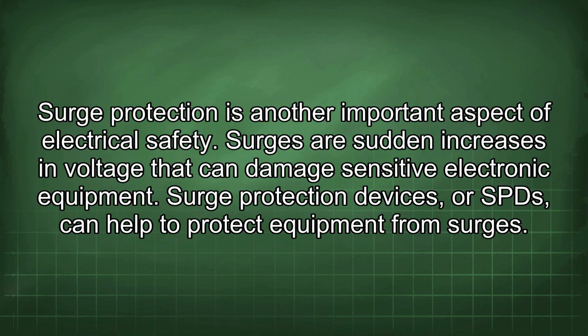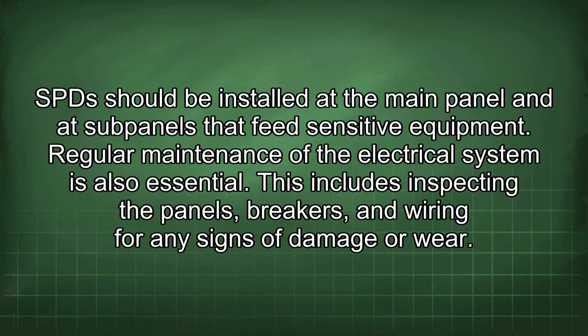Surge protection is another important aspect of electrical safety. Surges are sudden increases in voltage that can damage sensitive electronic equipment. Surge protection devices, or SPDs, can help to protect equipment from surges. SPDs should be installed at the main panel and at subpanels that feed sensitive equipment.